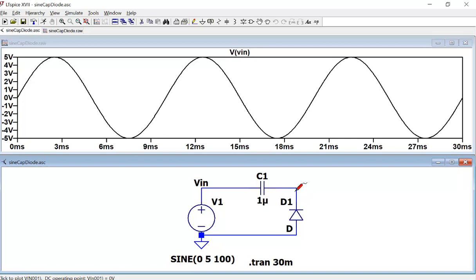So whenever the voltage here is lower than 0, lower than here, since here is permanently 0 volts, the ground is going to dump current into this node and pull it down to ground again. So it's going to be either 0 or up. Okay. However, the lowest voltage here is 0. Okay, that's a conclusion for now.